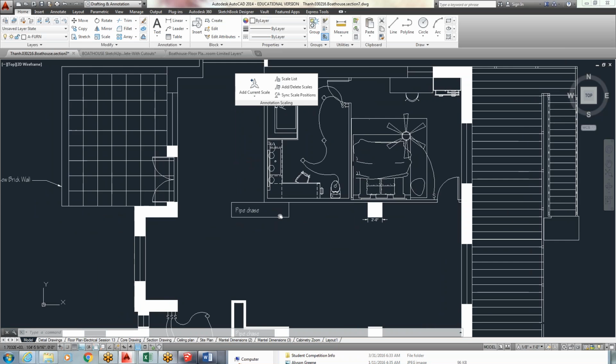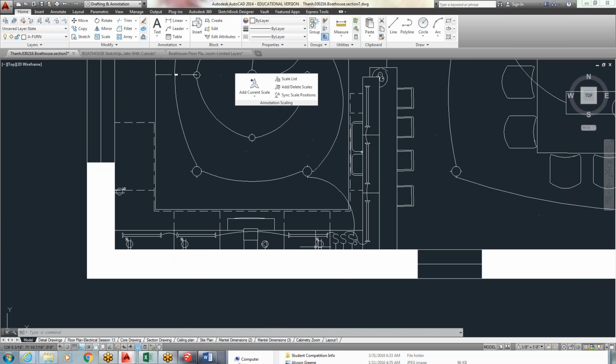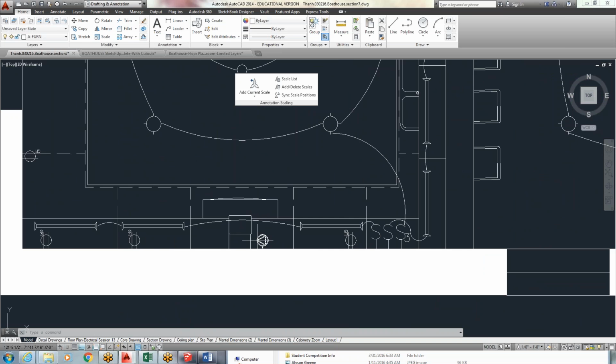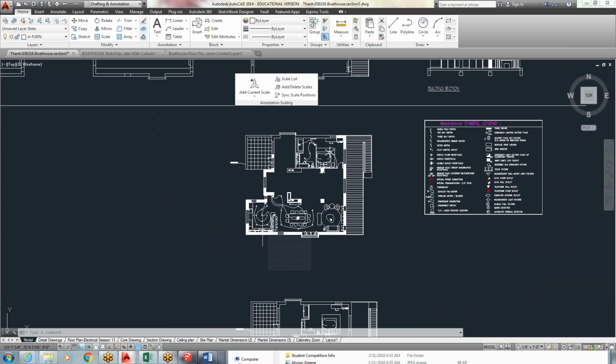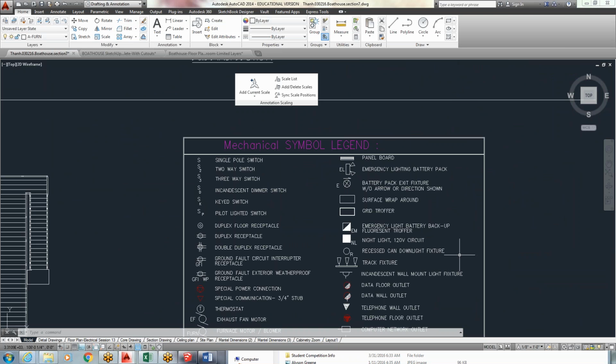Mechanical items like your ground fault circuit interrupters. For your kitchen and bath, they have to be those. They cannot just be basic receps. They can't just be the 120 volts without the ground fault circuit interrupter because of moisture issues. So the same thing, if we have this hood, I'm expecting some type of place for that to plug in and vent. I will be supplying you, well actually I've already supplied you with this drawing over here to the side.